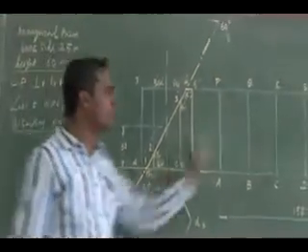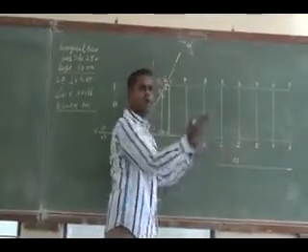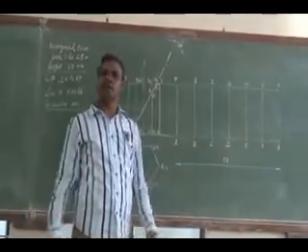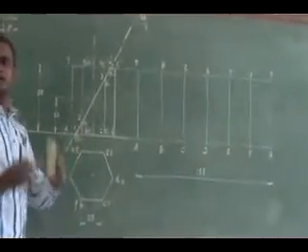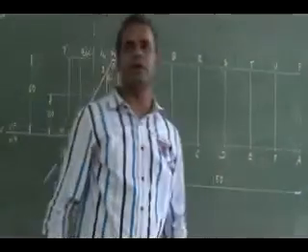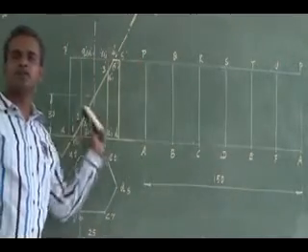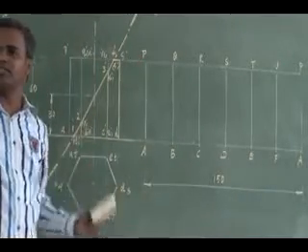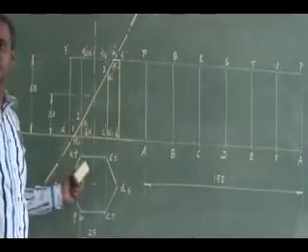Once I am able to mark that in my development, the retained portion alone I can darken. Okay, if I fold that, I will get the final part. That is the retained part development. So how can I mark these cutting points on my development? You see, carefully look at the notation: where the cutting points fall exactly, on which vertical edge or on which base edge. That is very much essential here.